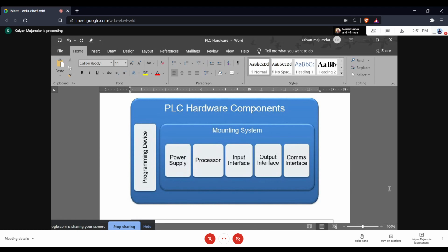It could be what is more commonly referred to as discrete input or digital input. That is a two-state variable. For example, the state of all kinds of switches, whether it's a manual switch, a proximity sensor, a limit switch, a temperature switch, a flow switch, and the list goes on. All these devices provide you with a two-state output. So any hardware that is designed to accept such a two-state signal is referred to as a discrete input or digital input interface. Similarly, you have devices which have two-state outputs.